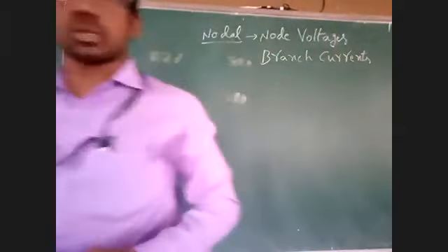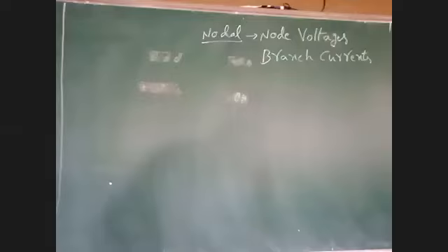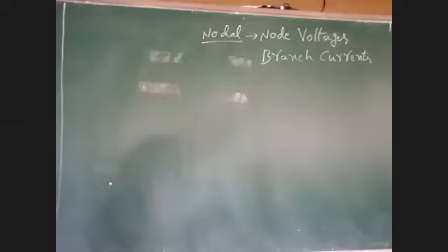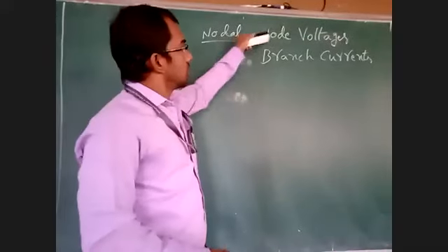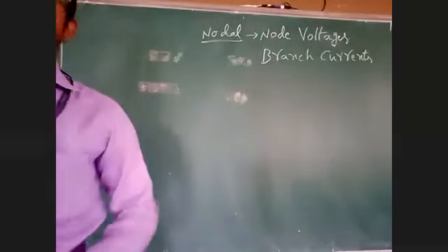But in mesh analysis, what have you determined? Loop currents, that is, closed loop currents. But in nodal analysis, we determine branch currents, the current flowing in a branch, and at the node point, what is the voltage.